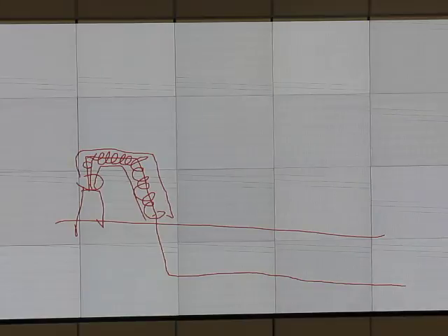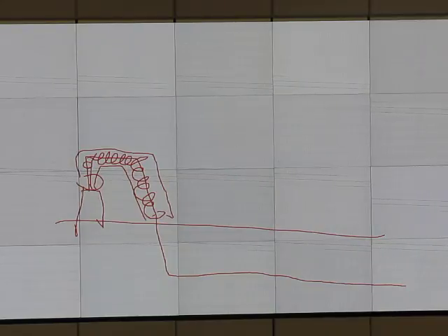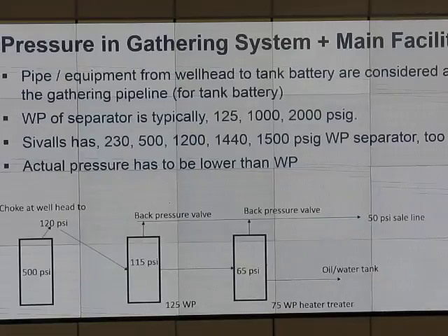The pressure is low enough and you keep it flowing. So if you have like 500 psi, probably you won't have a problem, especially if you produce a lot of water, because water carries temperature with it, right? And when you bury it, during the winter, if the temperature drops, you may not have hydrate, but you may have ice. If you have ice, it blocks the pipe. If it's too bad, it may burst the pipe and the pipe may leak. You don't want that, right? So you just bury the pipe below the frost line and let it flow. If it keeps flowing, you don't have a problem.